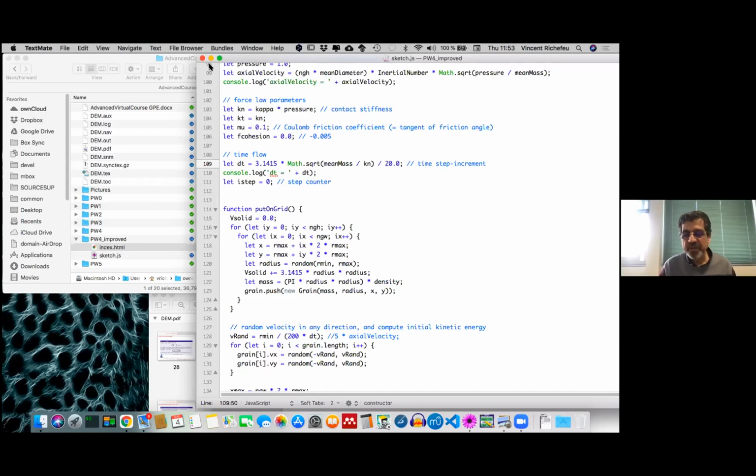It is the work by Nicolas Estrada and collaborators who showed in a very detailed manner that we can use the rolling friction as a measure of the angularity of the particles. Not with the same mechanism, I mean, it's not a moment, but angular particles, because of face-face contacts between particles, also can transmit a moment. So we can use it.